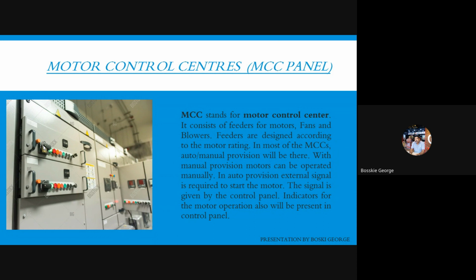But when we go deeper into the selection of starters, we come across different criteria. Some motors need smooth starting and smooth stopping, so we select VFDs, as with conveyors. All these MCC motor starters are selected according to the application: what is the machine, and which machine is coupled to the particular motor. That determines the starter selection.